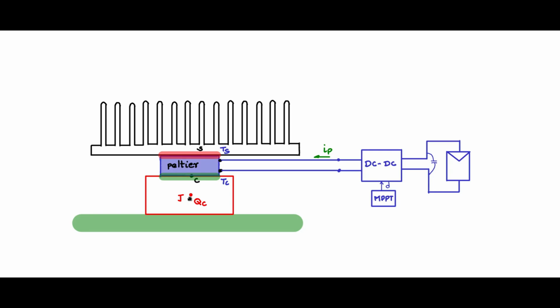So therefore it is not enough if you only make the Peltier junction remove the heat from the cold side and put it into the hot side, but you should also design your system in such a way that this heatsink is capable of removing the heat out from the sink into the ambient at that same rate. Only then the whole system together will work properly as a cooler.